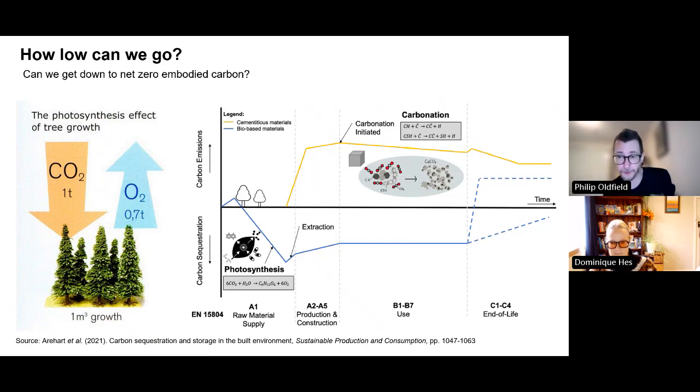and you can count that towards embodied carbon if you're careful. But you can see at the end of a life, if you burn that timber, it releases all those emissions straight out. If you landfill that timber, it slowly releases it over maybe 200 years. If you recycle that timber, that's great, but the next building gets that benefit, so the benefit's passed on. It's a lot of complexity there.